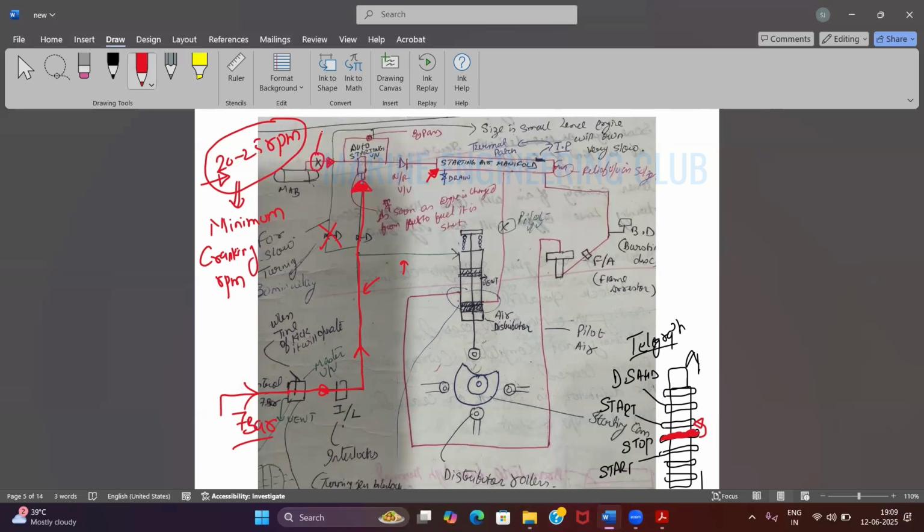During each maneuvering you are opening the air bottle valve. Yes, sir. So this is that manual valve. You open it, but until this air comes, the starting air will not go forward. Now suppose the 7 bar air has come, and air is going further through this non-return valve into my starting air manifold, and this starting air manifold will be completely filled by 30 bar air.